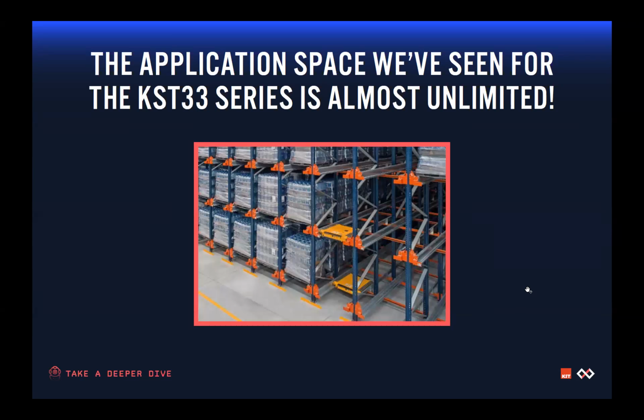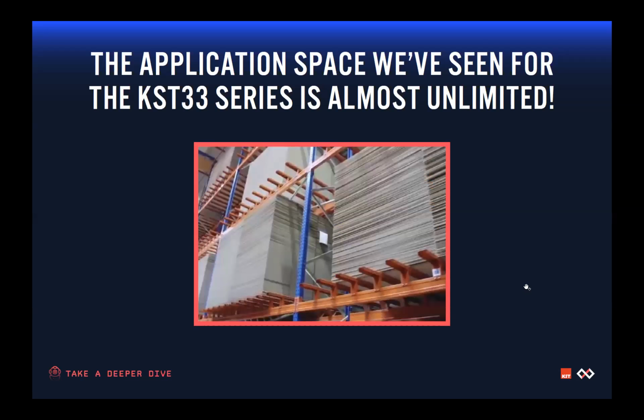We've even had applications in warehouses where people have installed a KST 3320 to see how many pallets exist in a certain bay, or whether or not a pallet full of product is getting empty or not. And in some cases, even measure how quickly is that product running out, which is awesome. And so we can use the power of a distance sensor coupled with an IoT platform like Losant to really make that application sing.